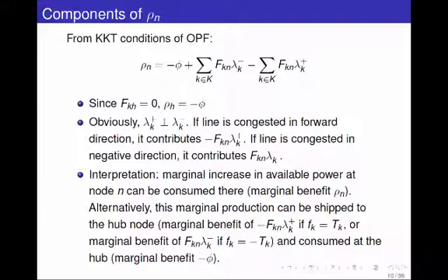Well, the lambda minus is basically 0. Since the lambda plus is positive, the lambda minus has to be 0. We argued that earlier. So we're only going to pay attention to this term here. The PTDF for this line is minus 1, so the minus with a minus becomes a plus, and we're left with this lambda k plus. Clear? So we have these two quantities. Basically, all this is saying is that rho B is rho A plus lambda AB plus.